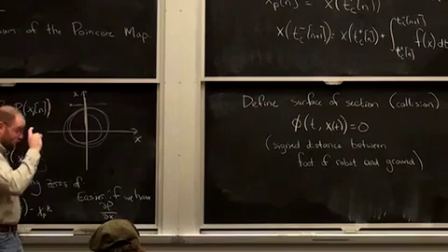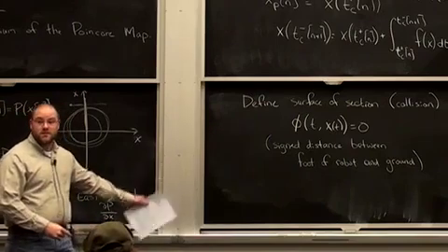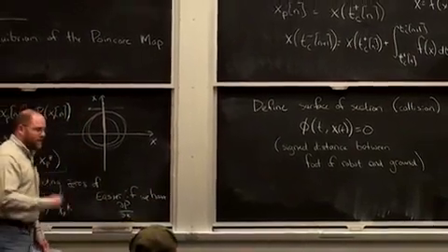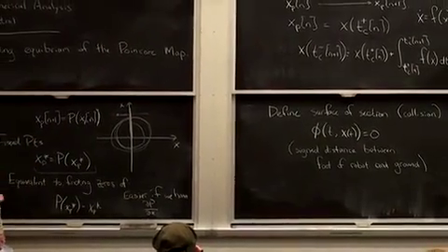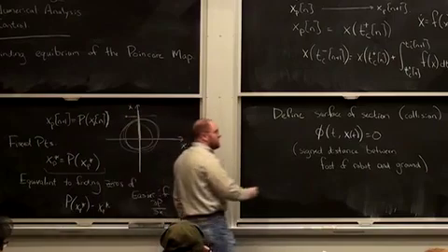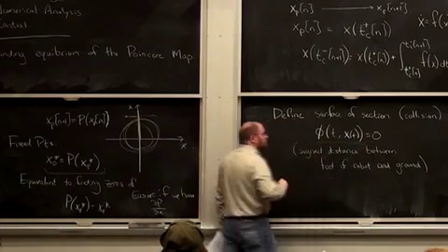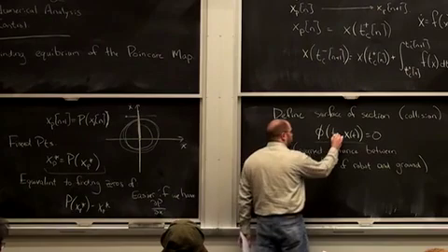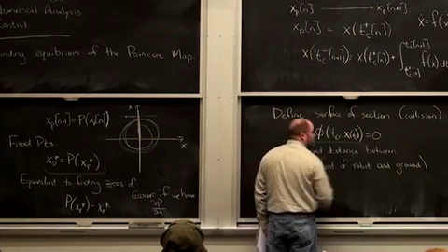So when the robot's foot hits the ground, that thing's going to be 0. When it's below the ground, it'll be some negative distance. When it's above the ground, it'll be some positive distance. Okay? And that's going to allow me then to define this at a time of collision. This thing had better be 0.